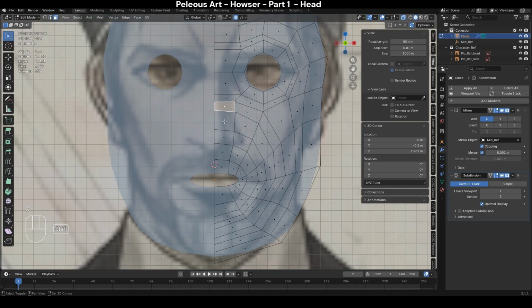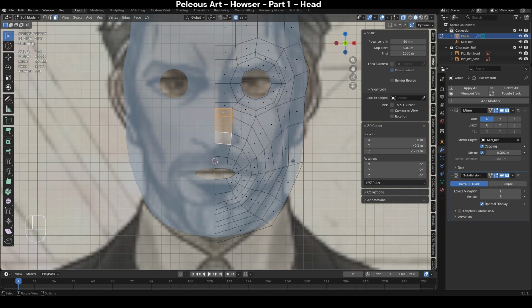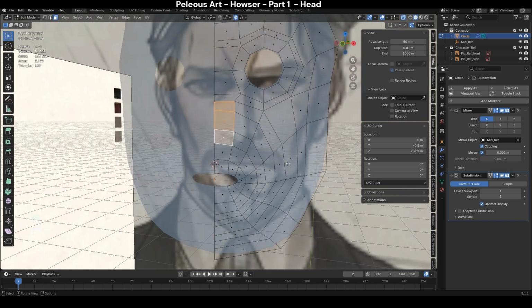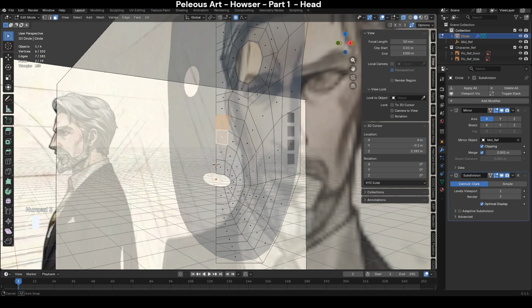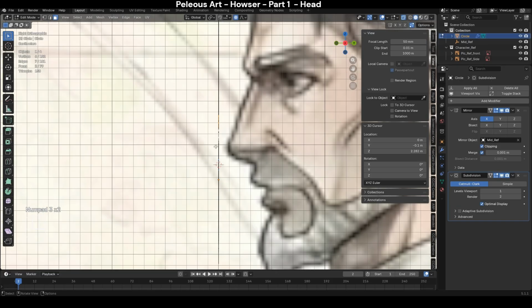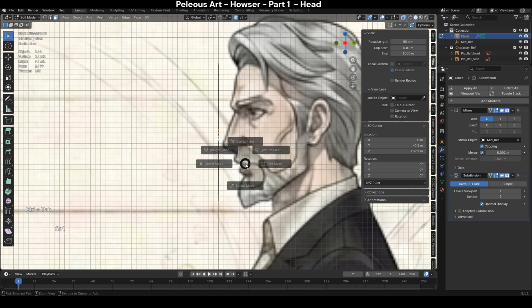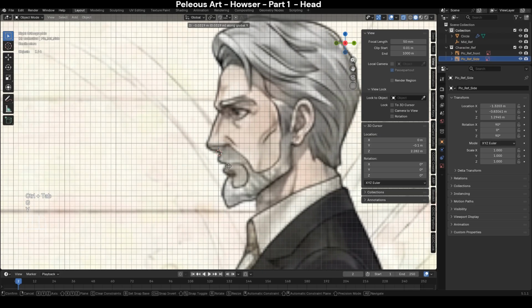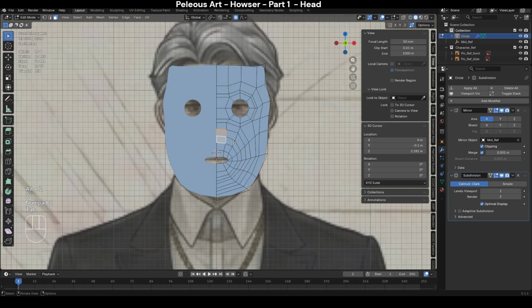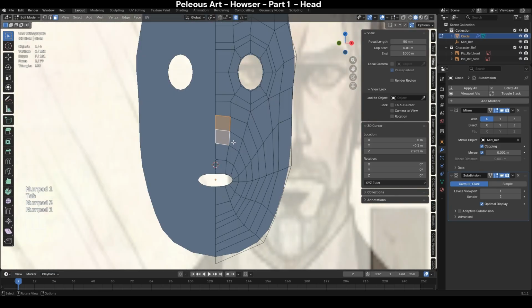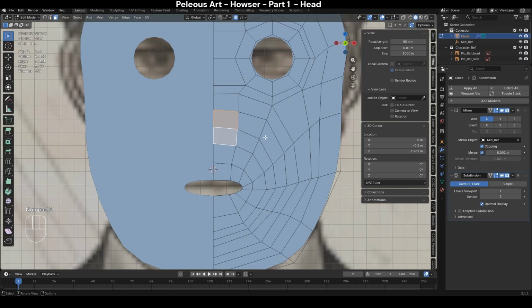Let's select those faces again with Shift and 3 to see the faces. Then we can select it. You can click on C, by the way, to select multiple faces with the circle and not one by one. 3 to go to the side view, just to ensure that when we begin the nose, so G Y to move it closer to the middle. And now when we extrude the nose, it will reach approximately the same point as the reference.